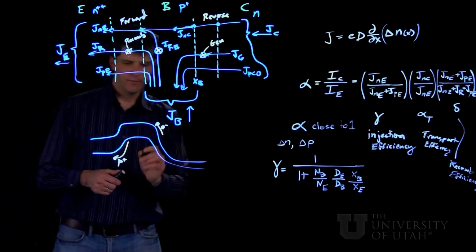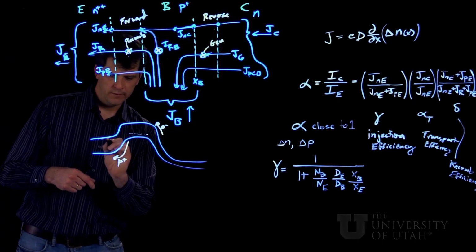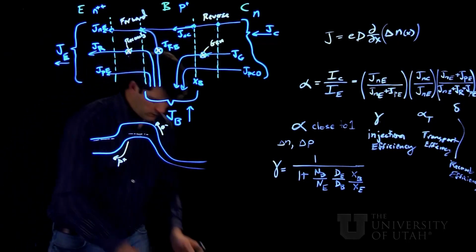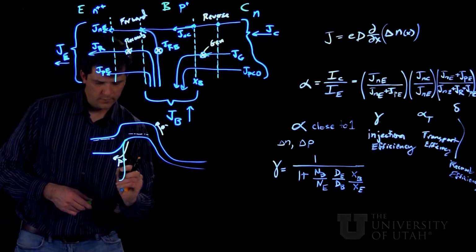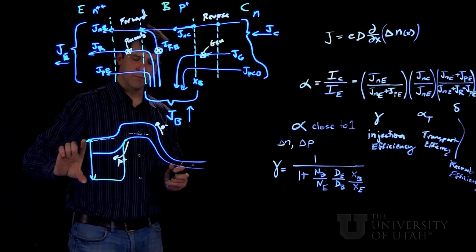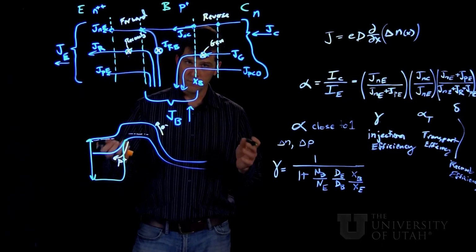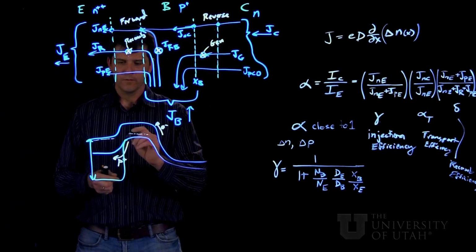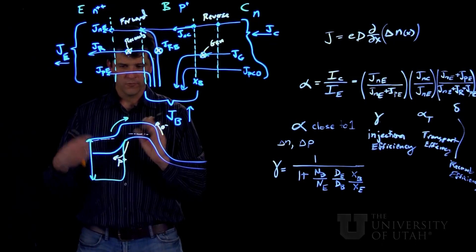So what we've assumed along the way here is that we're talking about a single material like silicon. But what you could actually do is greatly increase the band gap of the emitter here. And in a much earlier section, when we were examining PN junctions, we saw that the injection efficiency is greatly enhanced.